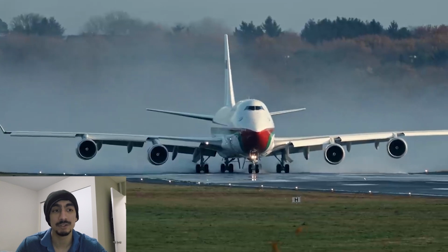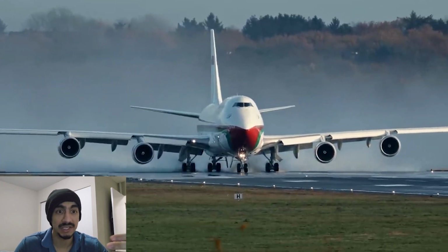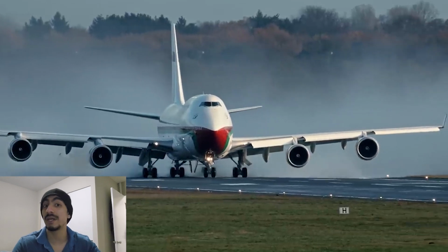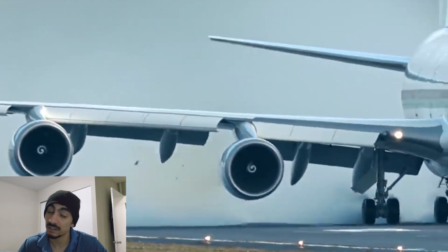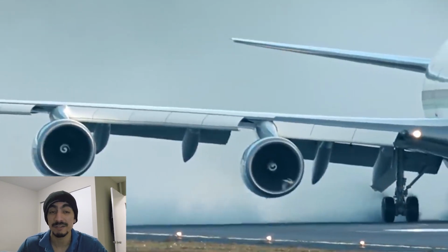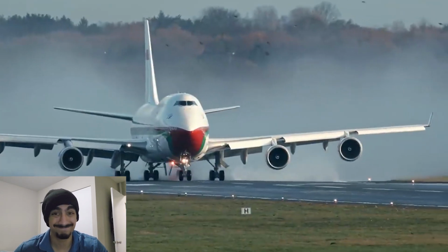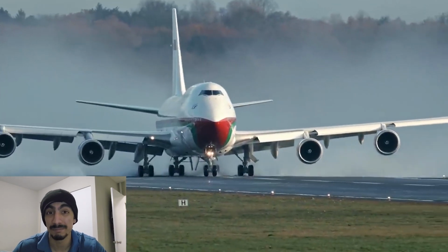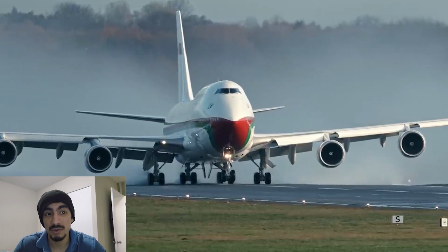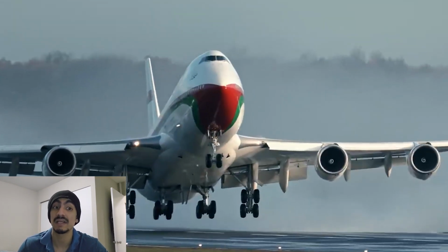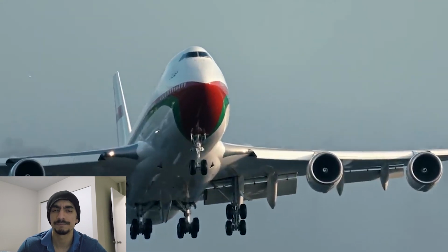And what that is, you don't want broken blades or any shrapnel busting through the engine casing and potentially damaging the plane's wing or the fuselage. An uncontained failure is very, very dangerous because engine fragments can cut fuel lines, it can cut hydraulic lines, it can sometimes even pierce passenger cabins. So that is why the engine core structure is designed to handle and contain most of the internal breakage.